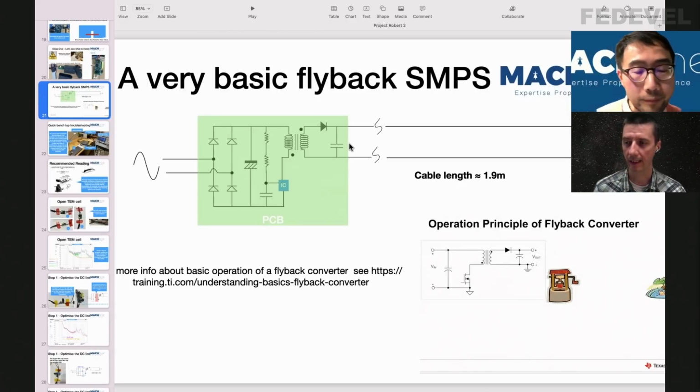Okay, and when they make it DC, there is this special IC which makes some kind of switching voltage from the DC, which goes through the transformer, correct? Yes. The IC is just like a switch, basically. It's what we call an isolated DC-DC converter. Like the buck converter we talked about last time is non-isolated, and this one is isolated because it's using a transformer. You use the transformer for isolation purposes. Yeah, because dealing with AC is dangerous, so normally they put in an isolated power supply.